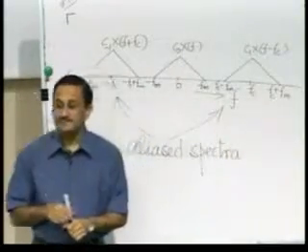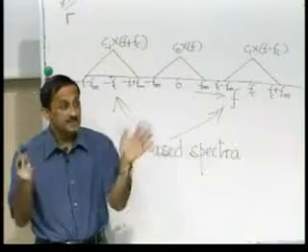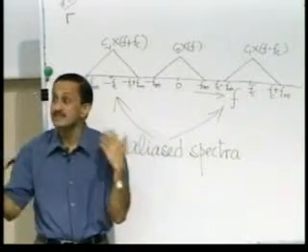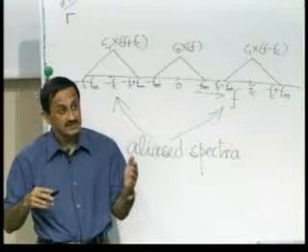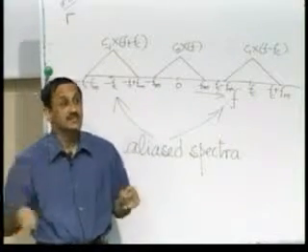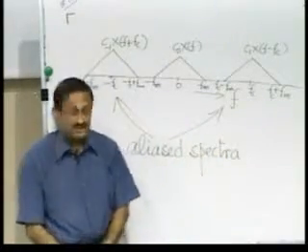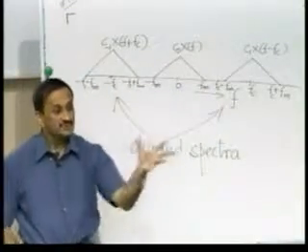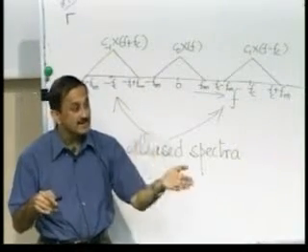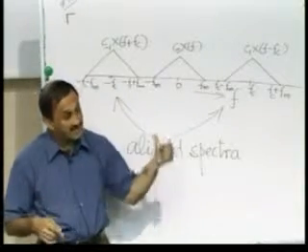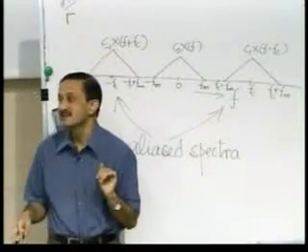Why are they called aliased spectra? Because they were not really there. They are false replicas or false apparitions of the original spectrum that have emerged as a consequence of sampling. That's a broader way to understand aliasing. In a certain sense, what we are doing is to create a false version of the original signal, because there are false replicas created. These additional spectral components are not really present in the original waveform. They have been created as a consequence of sampling. And in the reconstruction process, you are intentionally retaining the false ones and giving up the true ones. That's why we are calling this aliasing.